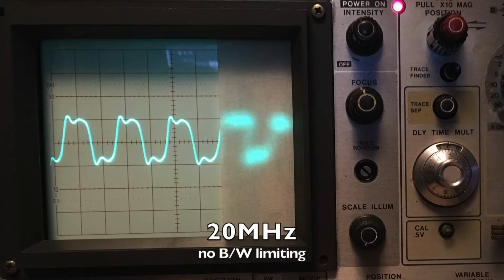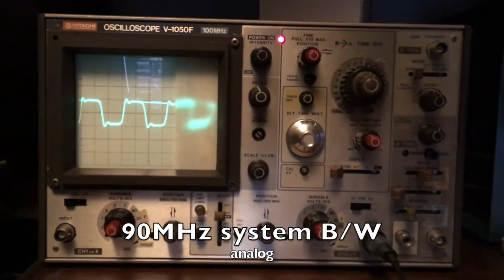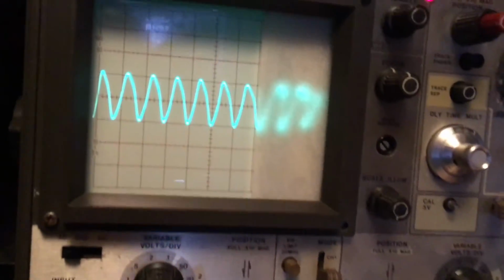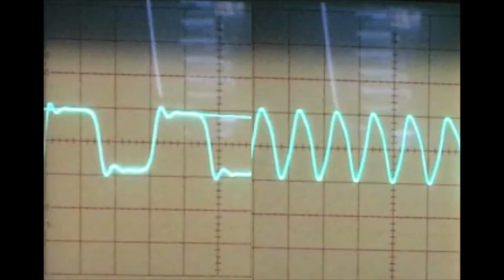This is what a 20 megahertz square wave looks like going into the front end of my 100 megahertz analog scope that has a system bandwidth of a little bit over 90 megahertz. Now, if I change the scale a little bit and change that waveform all the way up to 60 megahertz, this is what it looks like. Now, notice that as we expect, it's rounded off-ish into a sine-ish wave.